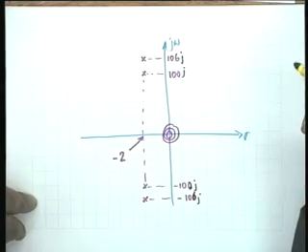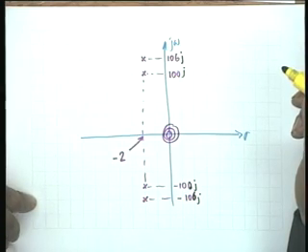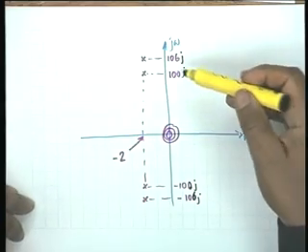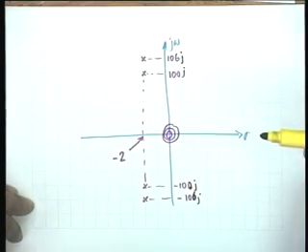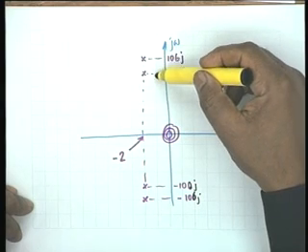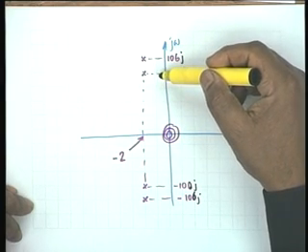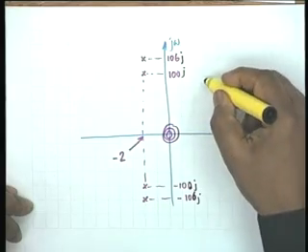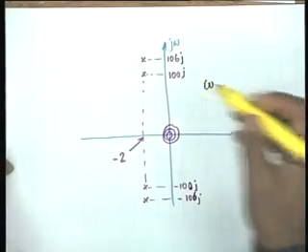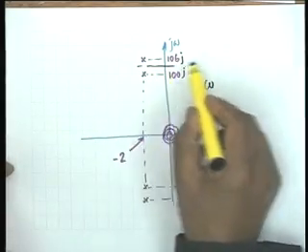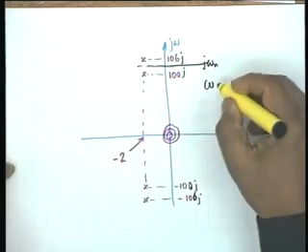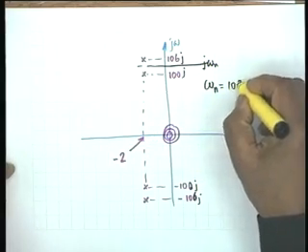We also assume that the coefficient of coupling is sufficiently small, which is suggested by the closeness of these two poles, and therefore our omega n, if you recall, this would be j omega n, midway between the two. So omega n is 103.